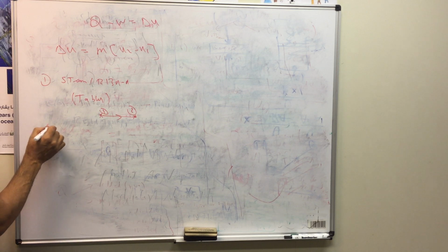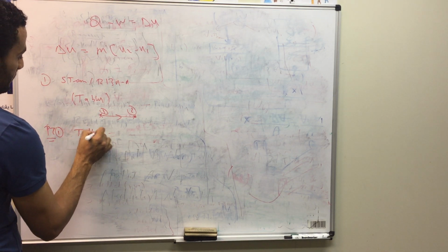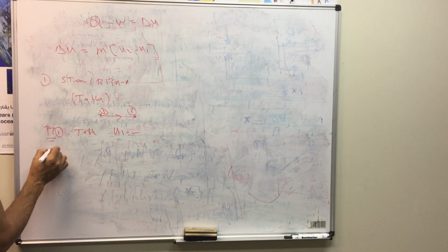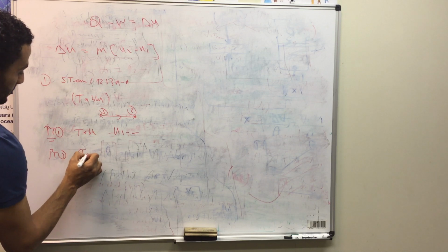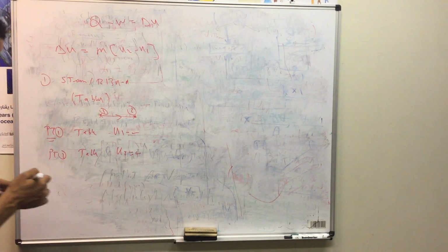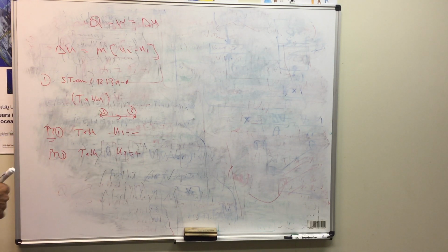So at point 1, we can just go to the table and get the value u1. And also at point 2, let's say pressure and temperature are given, then you can go to the table and get u2. Either this table is steam or refrigerant, you have to decide about the working fluid.